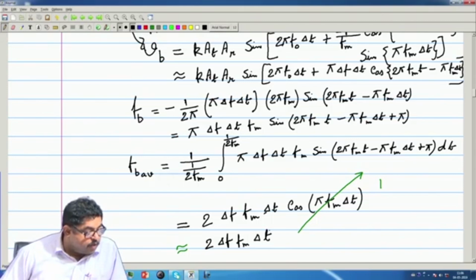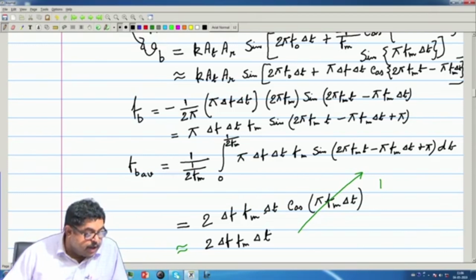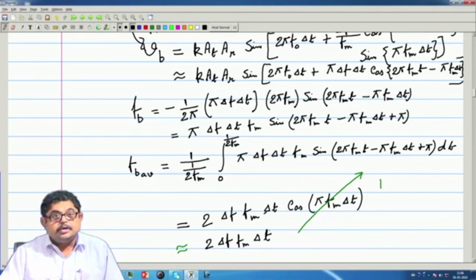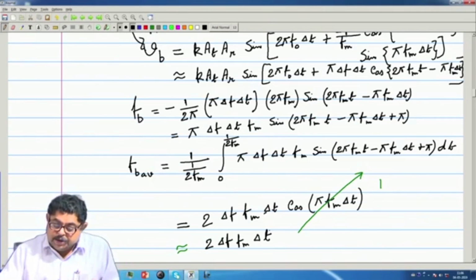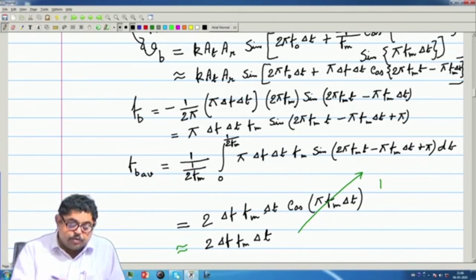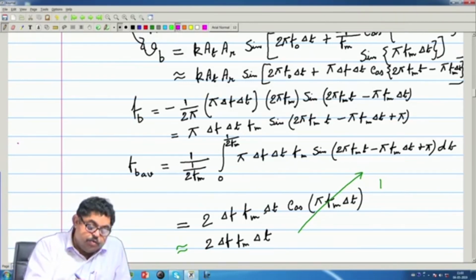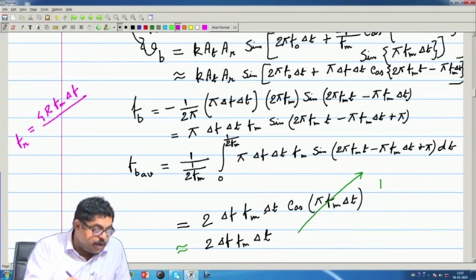Okay. Now, already you see these terms Δf, f_m, their product we have seen, because f dashed, that was Δf by 1 by f_m. So, Δf f_m, and from there we have related to R. So, we can immediately bring R here. Remember this, that already we have found that f_R is 4R f_m Δf by c.